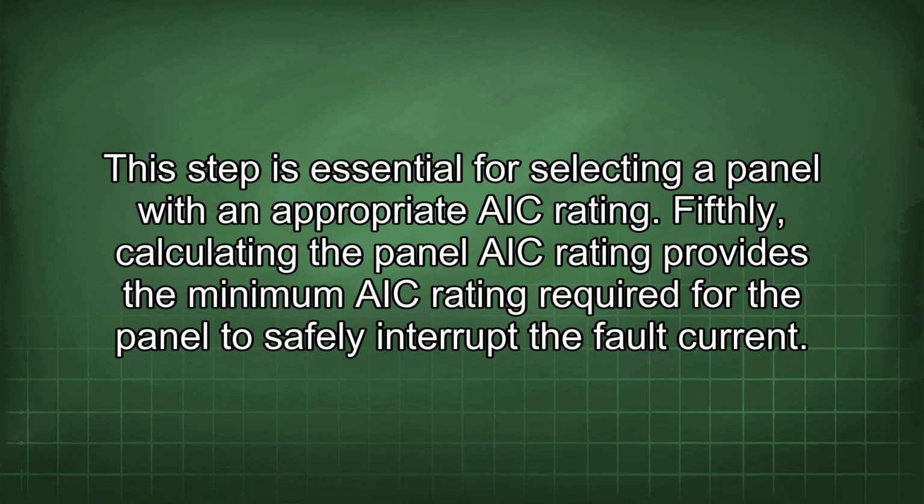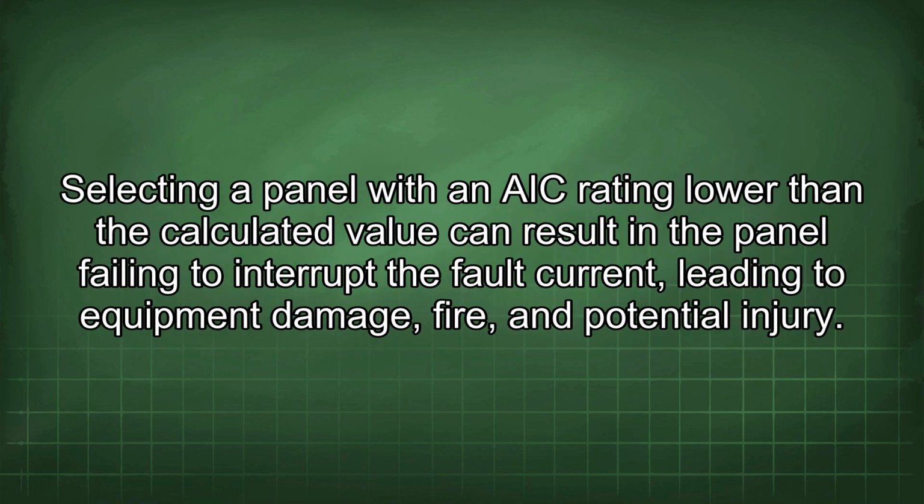Fifthly, calculating the panel AIC rating provides the minimum AIC rating required for the panel to safely interrupt the fault current. Selecting a panel with an AIC rating lower than the calculated value can result in the panel failing to interrupt the fault current, leading to equipment damage, fire, and potential injury.